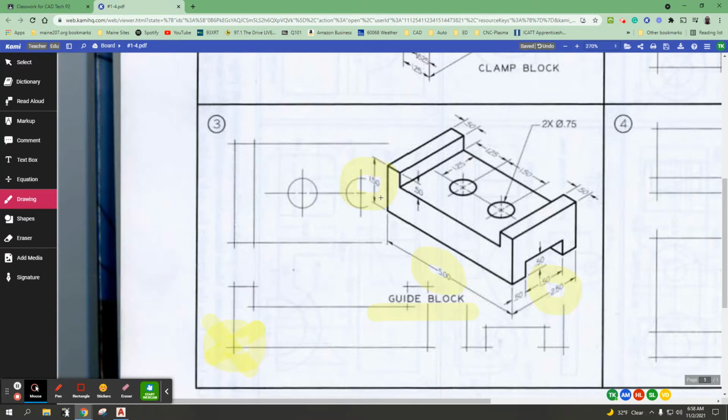So now I just set things in motion. I'm going to choose to go horizontally, so find the other side over here, and that'll be 5 inches over. Then I have to decide what kind of spacing I want to leave between my views. It's generally suggested that somewhere between 1 to 2 inches should work. Maybe a good place to start is a compromise between 1 and 2, and we'll go 1.5. We want to try to show the object as big as possible, and we also need to make sure we have enough room between the two views to put in a majority of those dimensions.